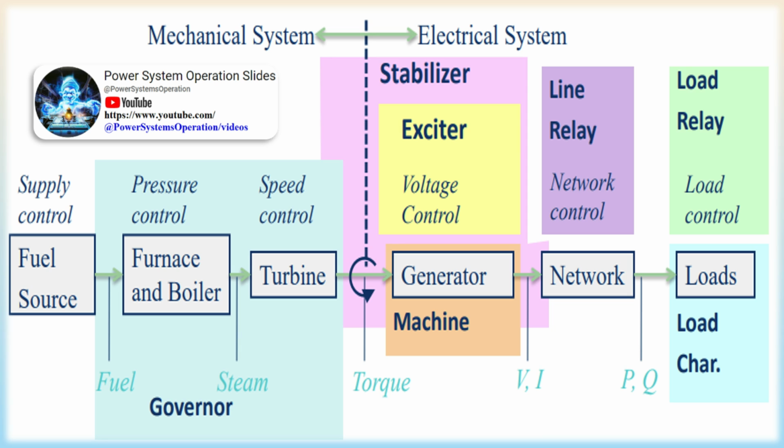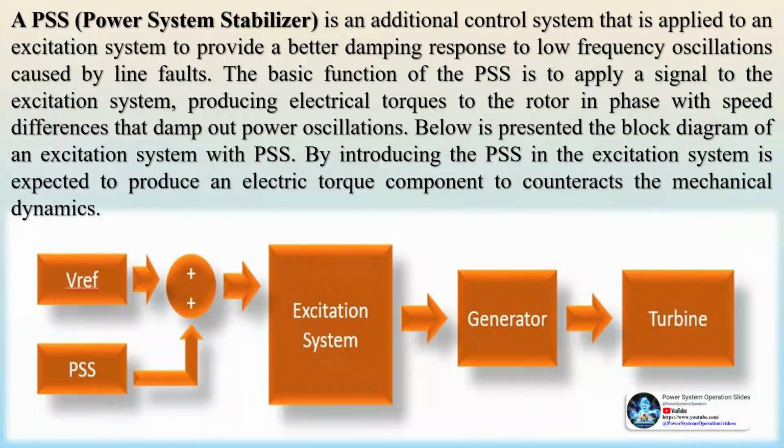These range from low-frequency intertie modes, typically 0.1 to 1 Hz, to local modes, typically 1 to 2 Hz, to intra-plant modes, about 2 to 3 Hz. The low-frequency modes, commonly called intertie or inter-area modes, are caused by coherent groups of generators swinging against other groups in the interconnected system.